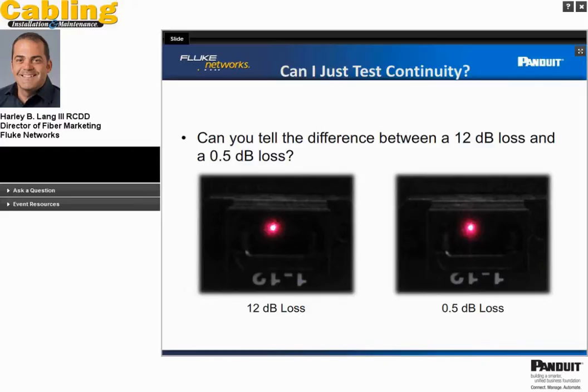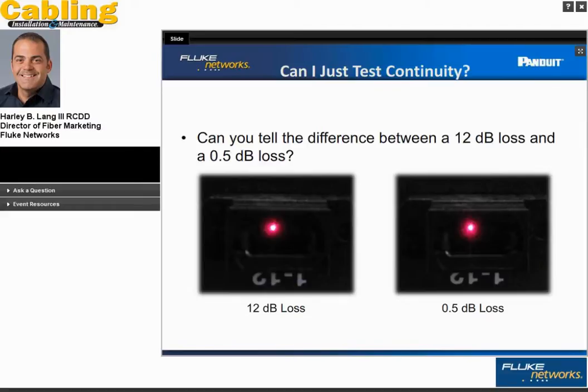So let's start out with a review of fiber optic field testing best practices, tools, and methods. I'm going to hit the high points here. The most basic tool that most technicians are familiar with is a visual fault locator, or VFL. In the old days, testing continuity was probably the most important thing for technicians, considering that our loss budgets were so high.